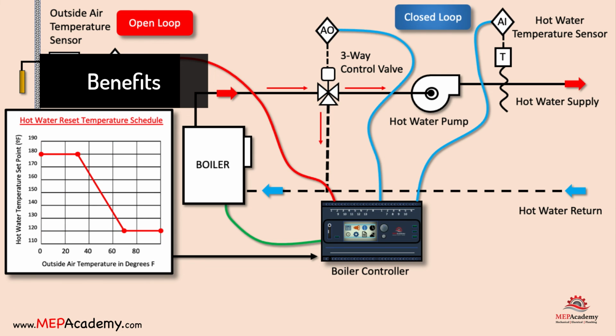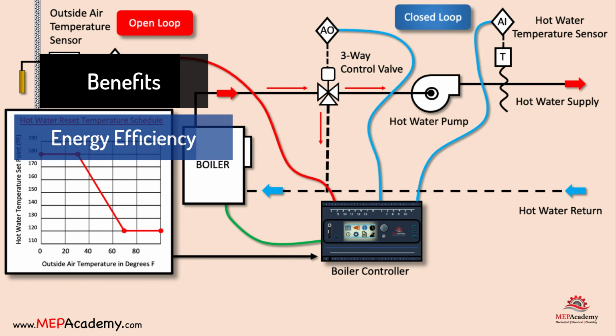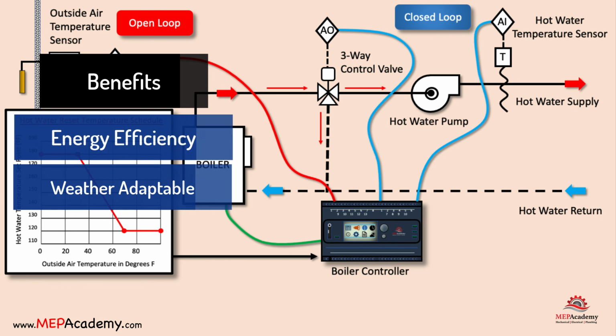Benefits: energy efficiency. By resetting the hot water set point based on outside conditions, the system optimizes energy usage by providing only the necessary amount of heat. Weather adaptation. The system can automatically respond to changes in external temperature, ensuring efficient heating in various weather conditions.